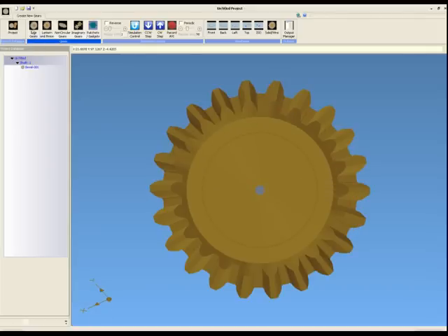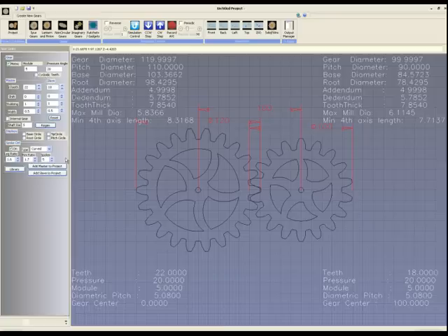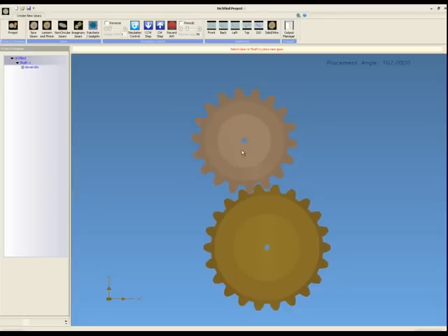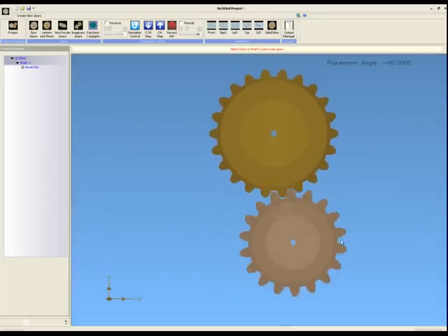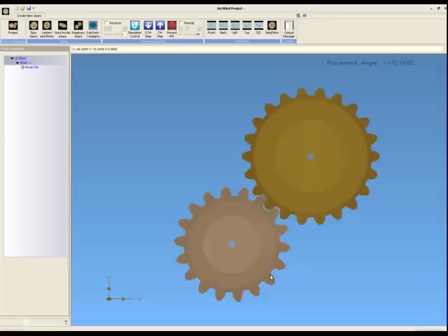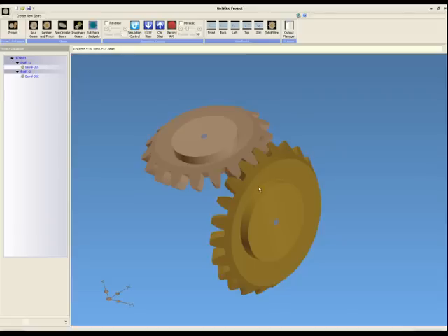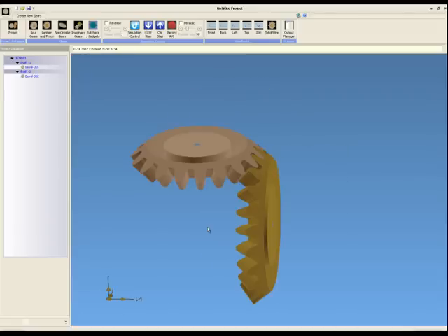Now let's pick a slave to put onto that gear. Let's go to the slave of the project, select bevel, and we want a straight gear, but we do want to check left-handed. As I said earlier, a left-handed bevel is needed when meshing with a right-handed bevel. And we will say OK. The system will allow us to click the gear to place it, and you can see it always rolls on the outside, which is not the way a bevel moves, but this is to ease in placing. So if we were to place this at 90 degrees and click, the system will rotate the gear down into place to create a proper bevel combination.